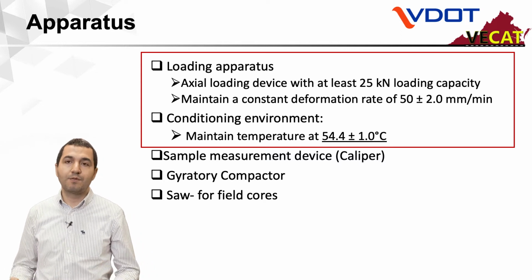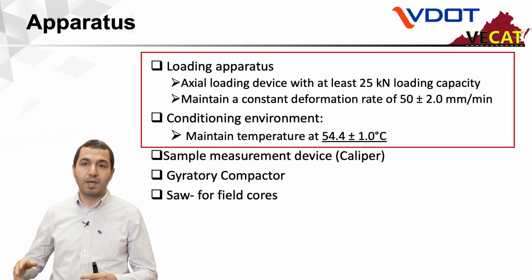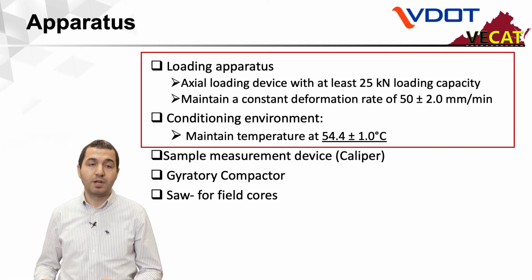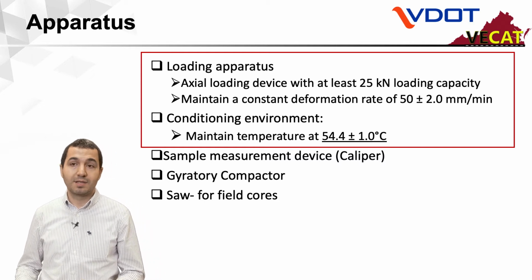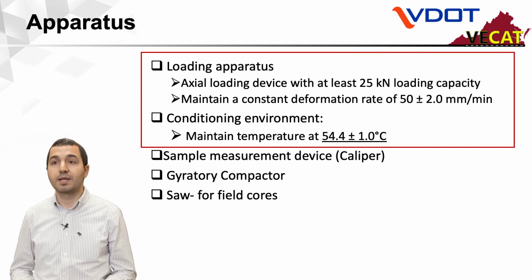The same apparatus needed for the cracking test is needed for this one, except that your conditioning environment has to maintain a temperature of 54.4 Celsius degrees. Other than that, the rest is the same as the cracking test.